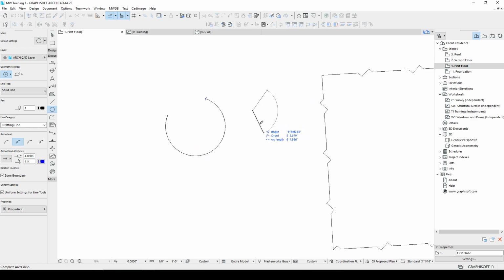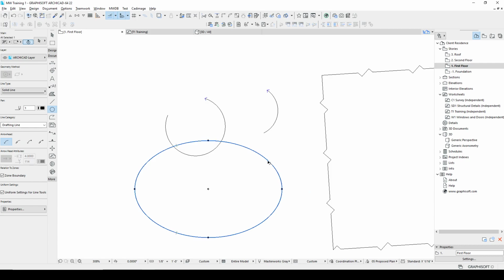At any of these times, we can use our keyboard to put in exact values: type the number, tab, type the next number, enter, and that ellipse then is contained within that box. And that is the type of ellipse geometry method that we had selected. If we want to do center and the corner of this apparent box, we would do the same thing.